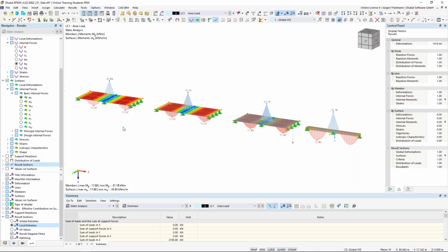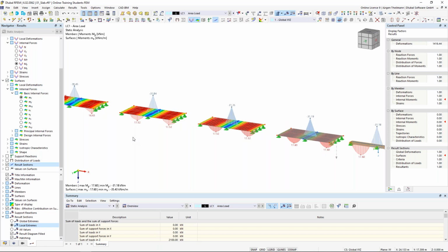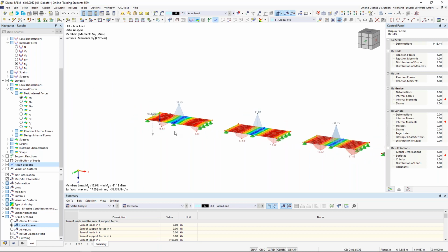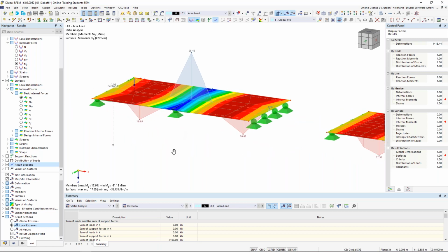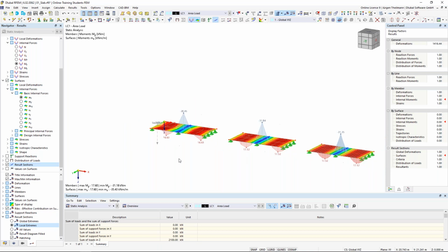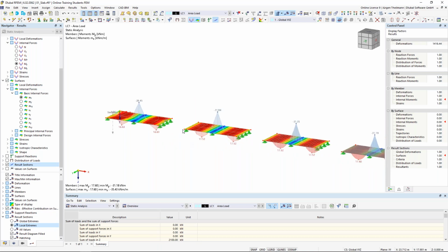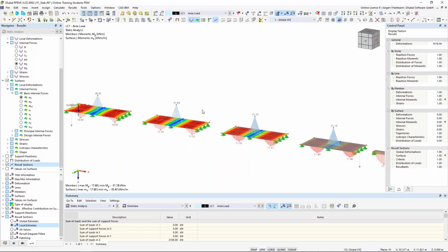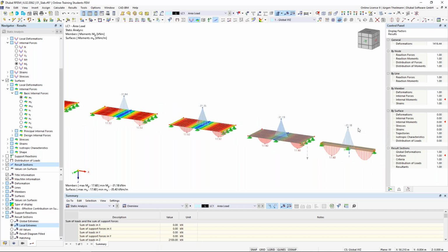Yeah, what we see right now on the very left, oops, it's here with this very coarse mesh. This is not a moment we would expect. This is very edgy, very coarse, and also the numbers are not what we would expect here. So we go to the right and we see the finer the mesh gets, the closer we get to the results of our beam.